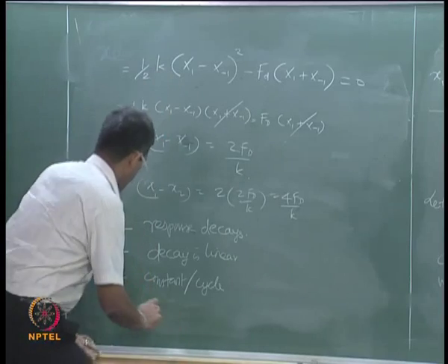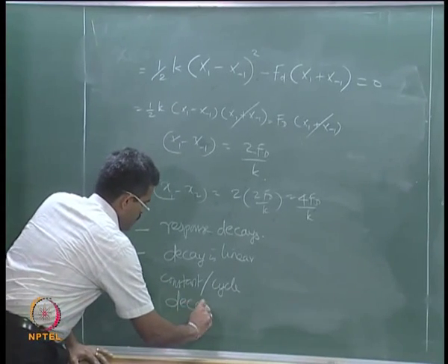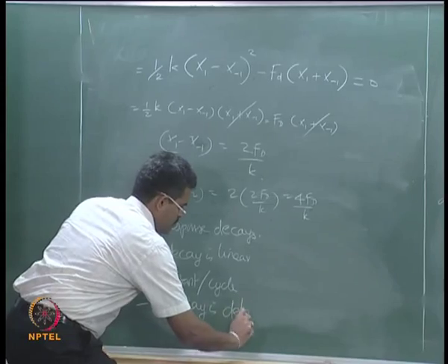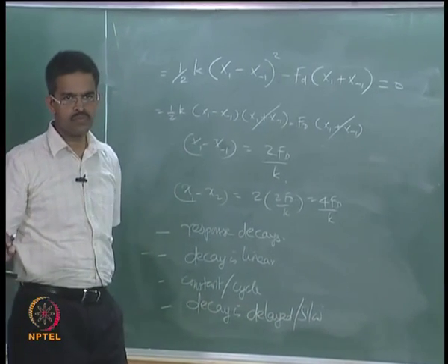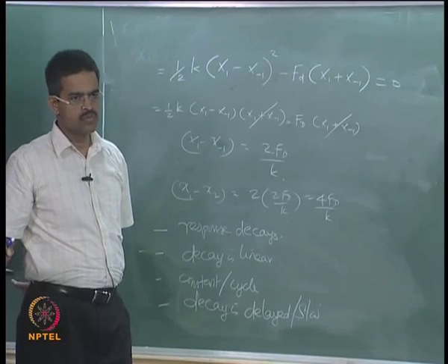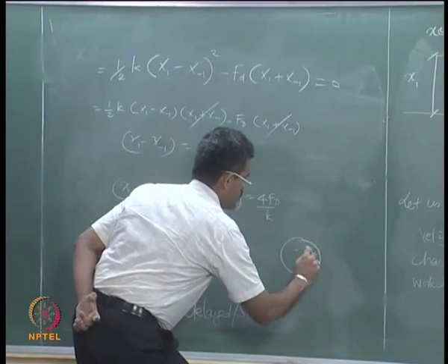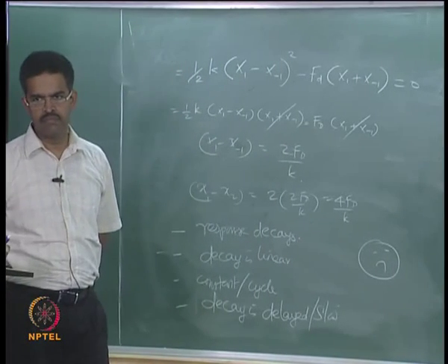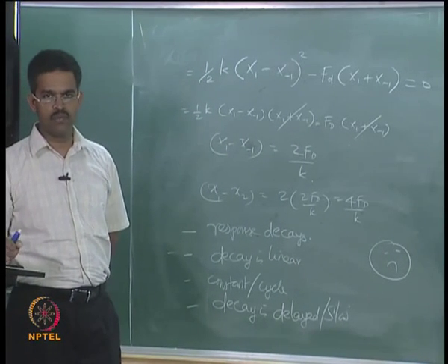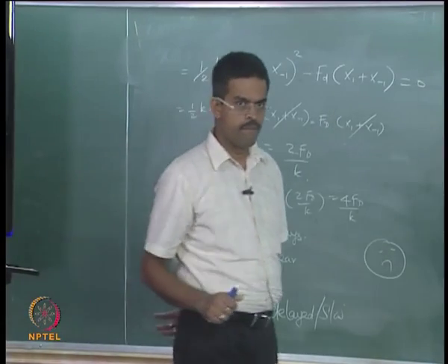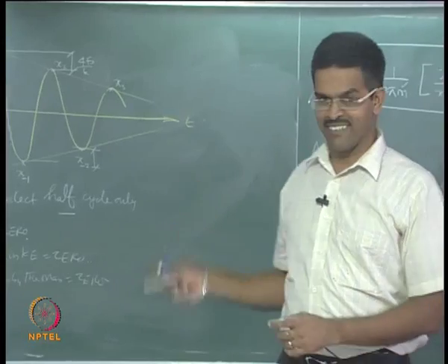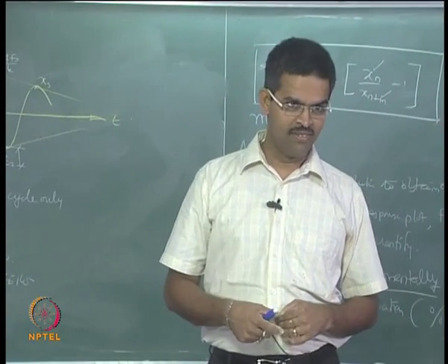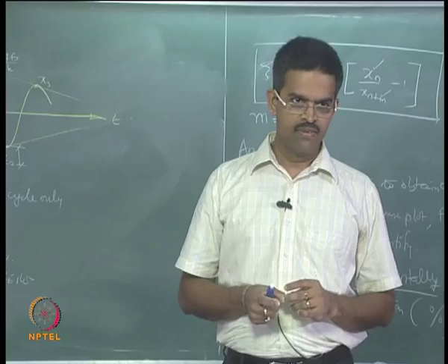Therefore the decay is delayed or slow, and hence it is not desired. Okay, it is not a desired one, whereas in viscous damping the decay is exponential, which is very fast. Here it is linear.